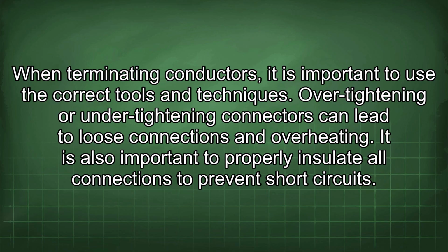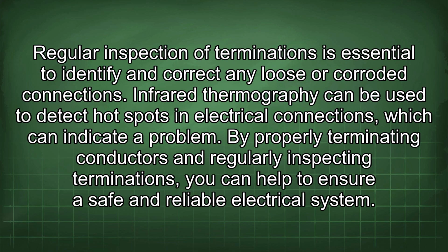When terminating conductors, it is important to use the correct tools and techniques. Over-tightening or under-tightening connectors can lead to loose connections and overheating. It is also important to properly insulate all connections to prevent short circuits. Regular inspection of terminations is essential to identify and correct any loose or corroded connections.